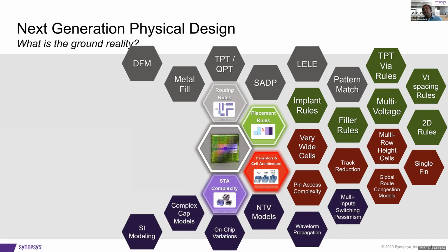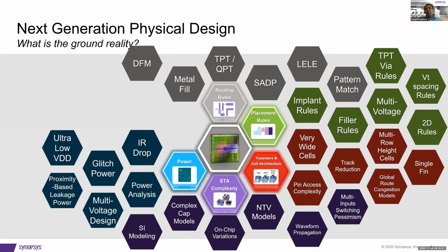Static timing analysis, just this component, variation analysis, SI modeling, and moments, LVF. It's an incredible amount of complexity that keeps coming into the problem statement. Similarly, power, right? Low voltage, so pretty much low VDD design has become very standard.